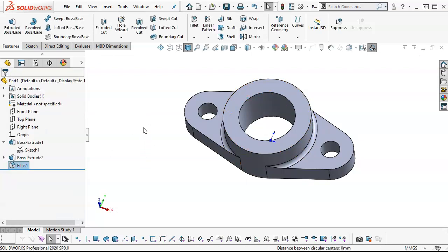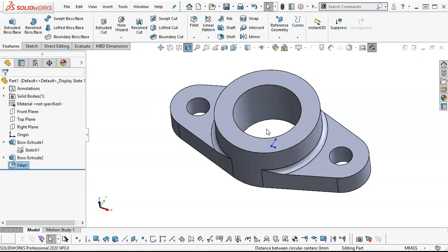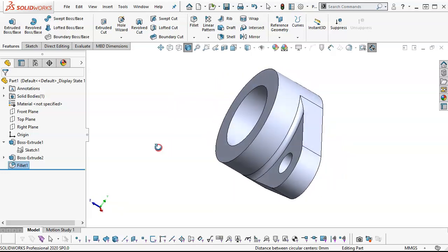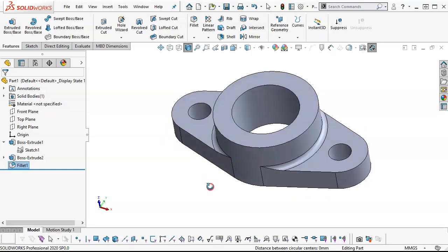So the manufacturing process, as the designer, I know that the fillets over this outside edge are going to be a little more difficult. Probably not 100% necessary. If we just kind of buff or break those edges with a file or deburring knife, it's going to be fine.